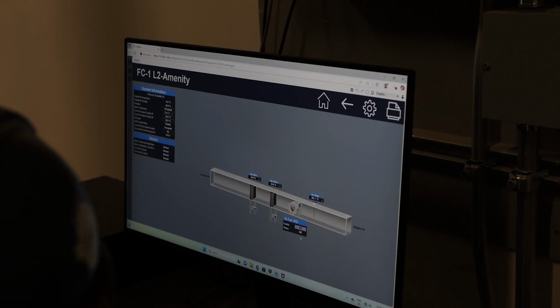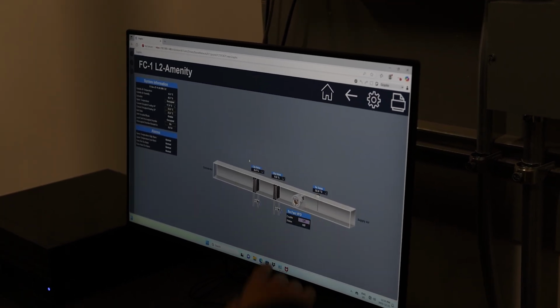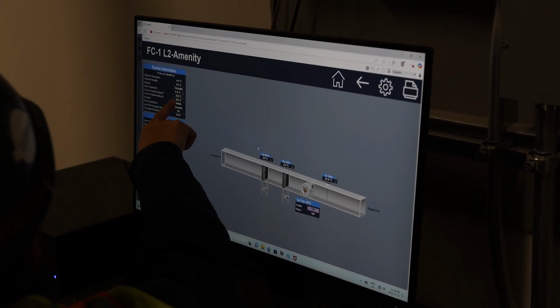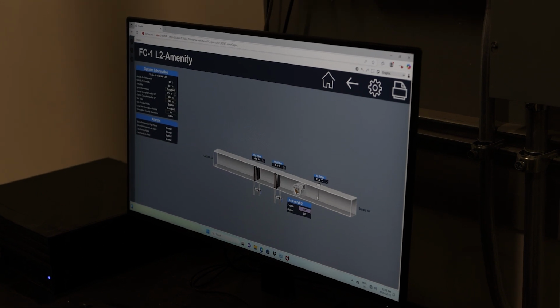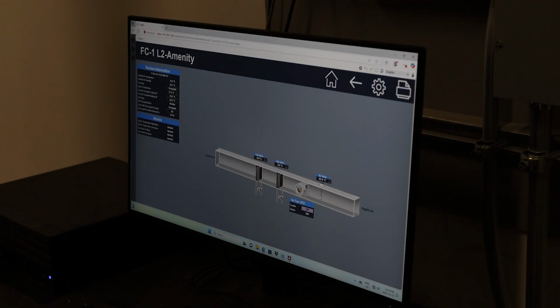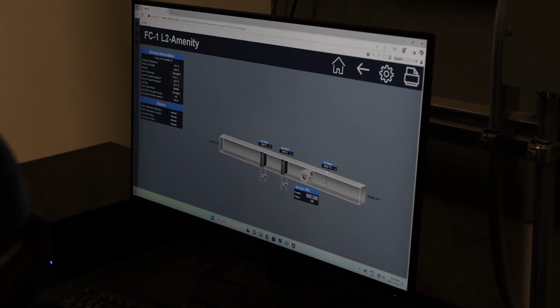So I know the fan is actually off, and it also tells us the discharge temperature. But the room is still only 18 degrees C. Our set points are 23 and 22. That's why the heating valve is fully open. It's just trying to give heat to the room, because some rooms are still not finished and the door will be open and closed.